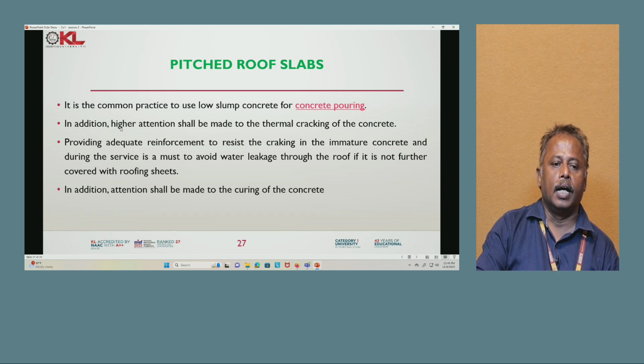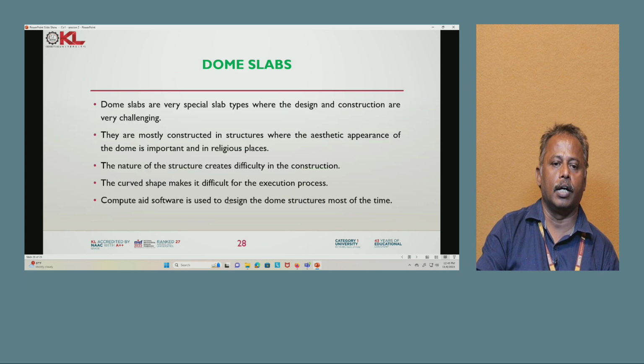In addition, higher attention shall be paid to the thermal cracking of the concrete. Providing adequate reinforcement to resist cracking in the immature concrete, and during service, is a must to avoid water leakage through the roof if it is not further covered with roofing sheet. In addition, attention shall be paid to the curing of the concrete.